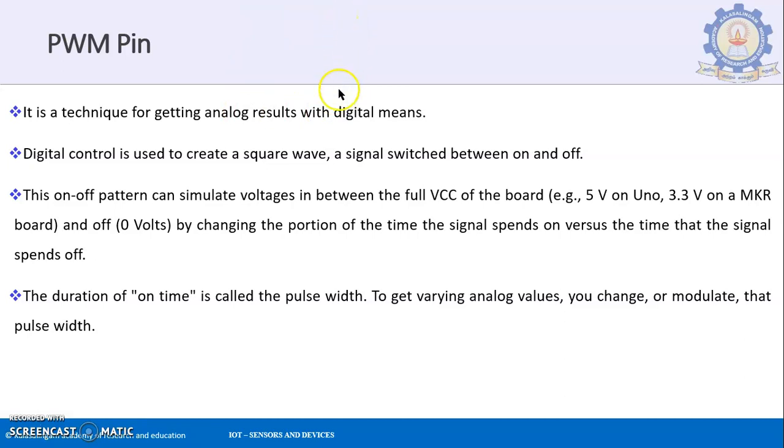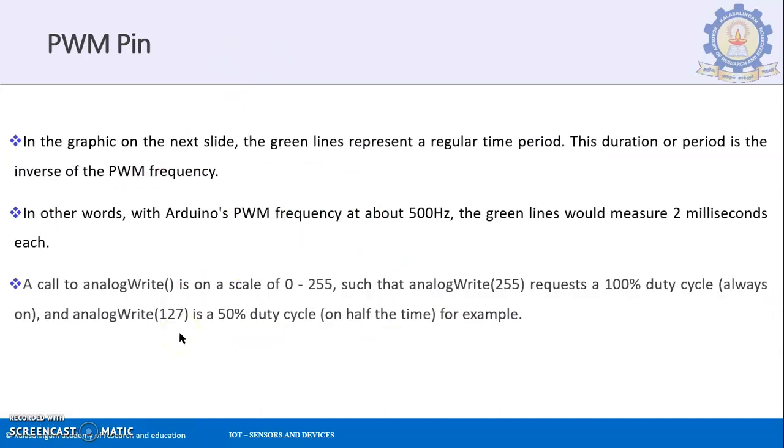That is, the on time will be 50% and the off time is going to be 50%. So 50% on time, 50% off time, totally one pulse will have 100%. The pulse width, normally being 50%, you can change from 10%, 20, 30, 40, 50 all the way to 90. If the on time is 90%, you know that the off time is going to be 100 minus 90, 10%. This is just an example for you to understand. We'll be looking into how it is happening.